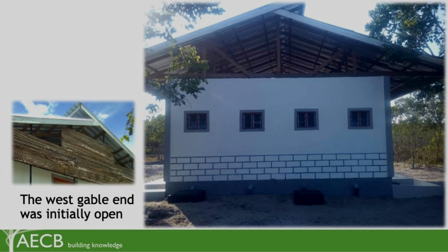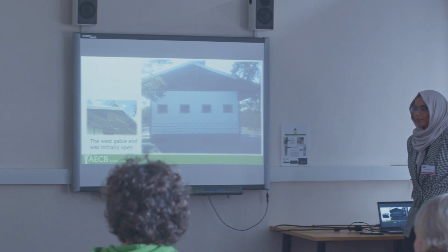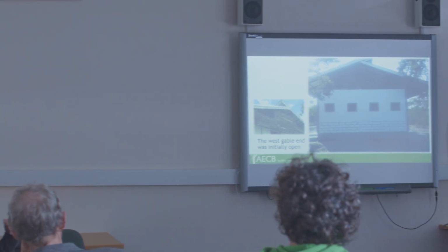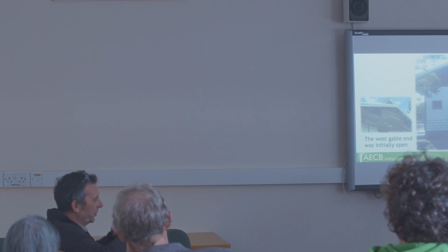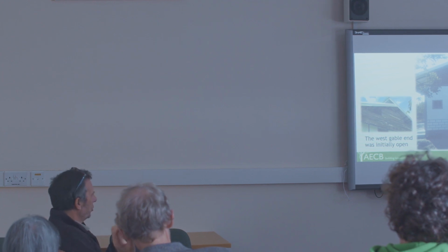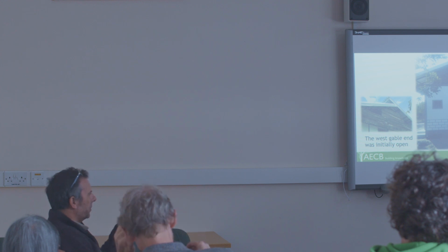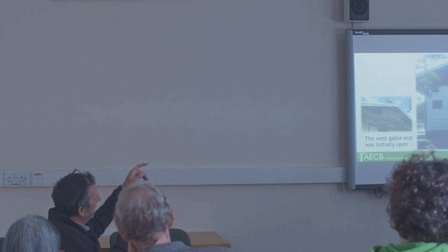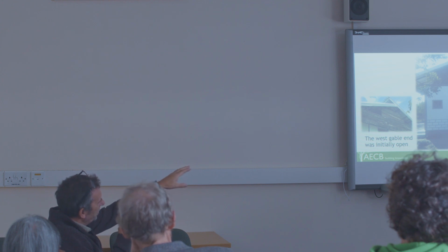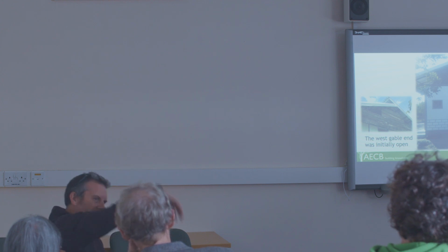And one of the practical things about that, if you just go back to that slide, so there are two modes: no sun, still humid weather, where we'll be relying on stack effect to help pull air through the windows and past your body and up and out. And then another one where there's a strong wind blowing, and it's a pressure differential from the front of the house to the back of the house, which will suck air through more powerfully, which is obviously a good mode. What we weren't sure about is what was the balance, and if wind was blowing through that roof, would it actually come down the rooms? You know, you've got toilets involved in this as well.